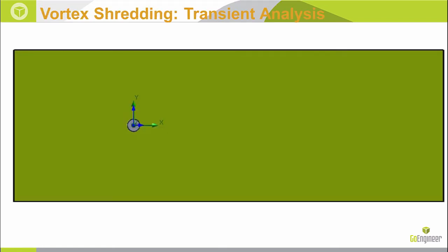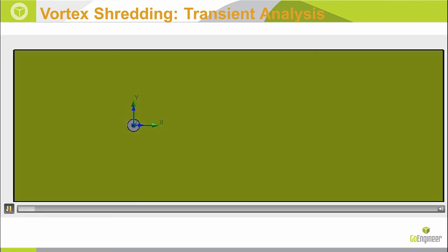Moving on, sometimes a steady state solution is not available. In this case, we have a cylinder with a high fluid flow around it. And if you look at this flow, there is not one steady state solution because of a phenomenon called vortex shedding. So what's happening is at a given point of time, you have a solution available, but there is no steady state solution irrespective of time, because this alternating pattern in its behavior constantly takes place based on the distribution in the previous time step.